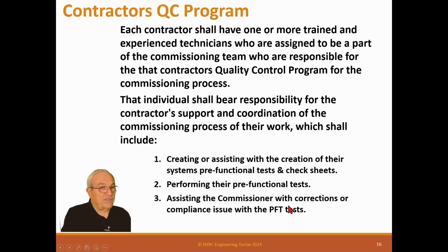Another big problem here is actually getting the sheets. Now, I come from a paper-based area. I have used some automated cloud-based systems, which are fine. The cloud-based are good because you can see what's missing right away. In paper, you have to go look yourself. So this is always a problem: we want to complete, but we can't complete because he's not complete. PFTs, pre-functional tests, have to be done before you can move on to other things that have to happen. So they need to get done on time.